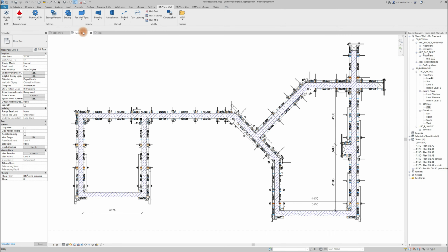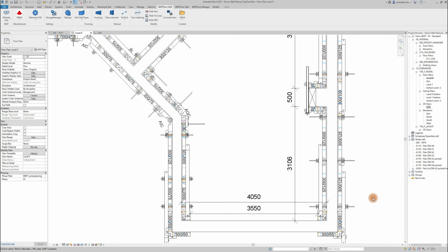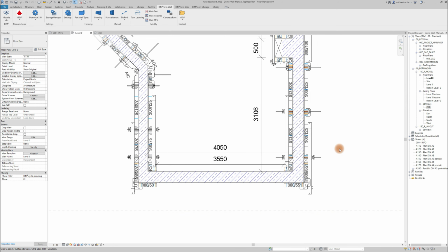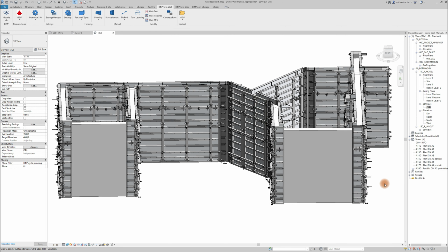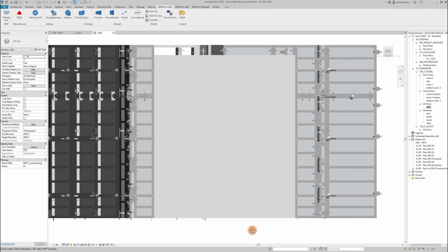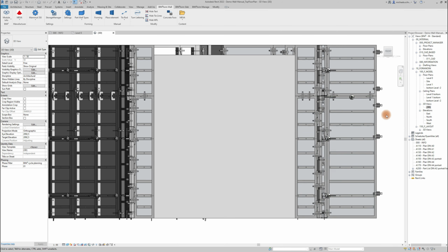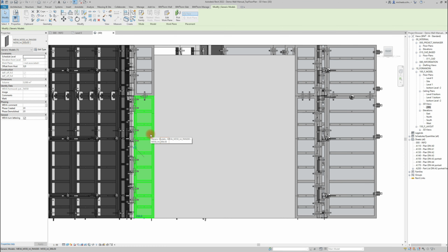To demonstrate this, we have created this simple floor plan where we have this wall left. Here you can see the measurements so that we know which element widths we can use. Since it is visually easier, we will work within the 3D view and therefore we select the front view. We want to use similar height constellations as the elements on the corners, so let's check what the height is first. This one has 3 meters.